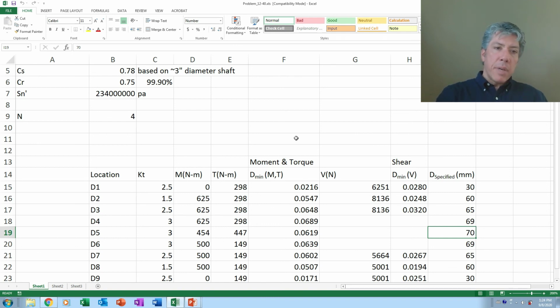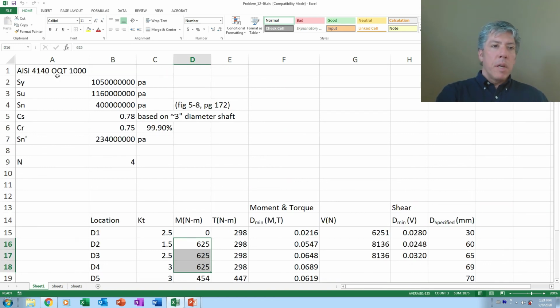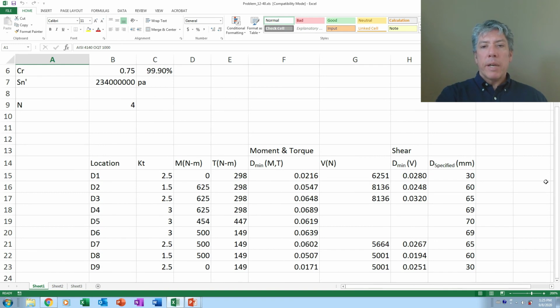Notice I've got a nice big safety factor here of 4. I've used the largest moments. So if somebody accidentally uses a material, or we get in a bad batch of material that's not quite as strong and somehow it slips through and the shafts are made, they're probably going to work anyway. And I think that little bit of cushion is worthwhile. So everywhere you see I've kind of chosen a conservative route.